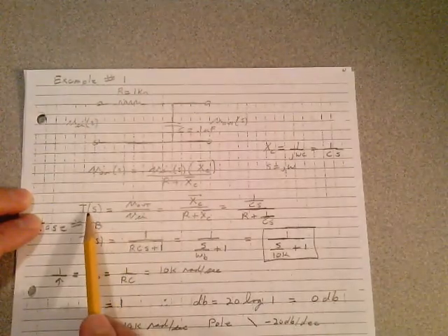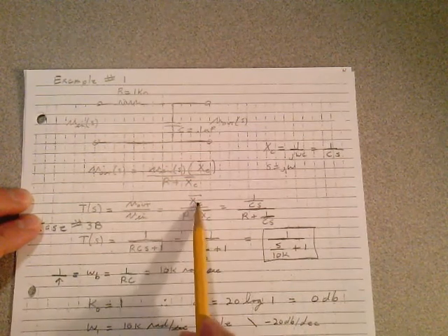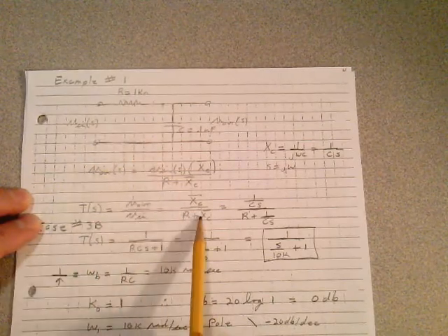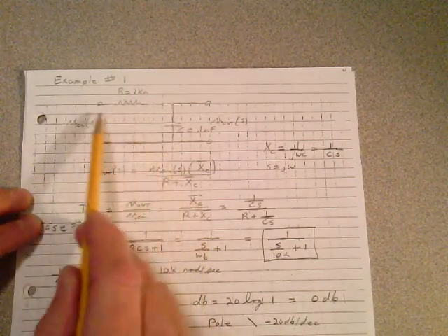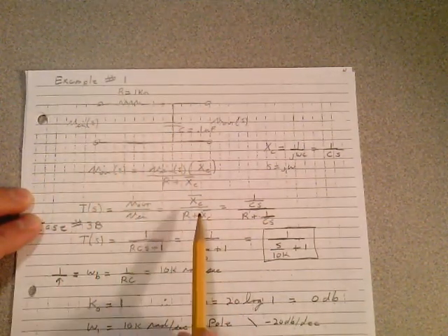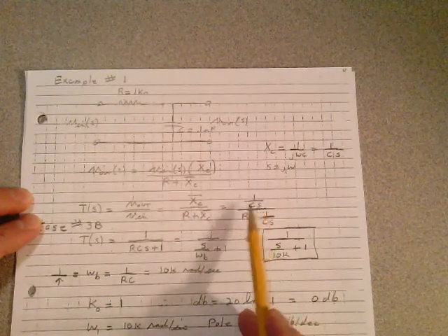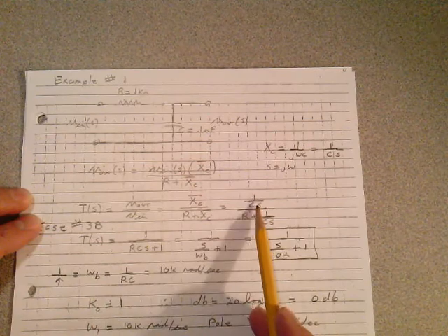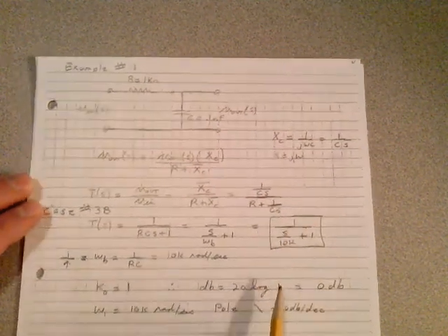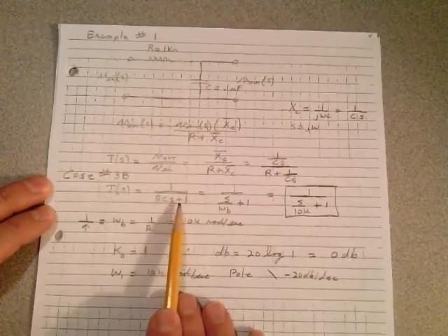So we know that the transfer function then, if we form the ratio V out over V in, is just the reactance divided by resistance plus reactance. And I told you, you should be able to go straight from the circuits to this transfer function. This transfer function for this circuit is this reactance divided by the sum of these two, the resistance plus the reactance. That's the voltage divider rule. Making the substitution now for X sub C, it's 1 over CS, that's the reactance, divided by R plus 1 over CS. Simple algebra. Forming the transfer function in a time constant format, it's 1 over RCS plus 1.